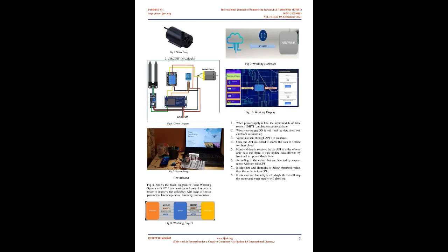3.2.1 NodeMCU. NodeMCU is an open-source IoT platform. While writing GPIO code on NodeMCU, you can't address the pins with actual GPIO pin numbers. There are different I/O index numbers assigned to each GPIO pin, which are used for GPIO pin addressing.